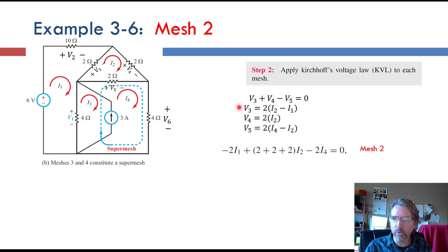Pay attention to the Ohm's law sign convention here when you're subtracting your currents and labeling the polarities. When we combine these together, though, we get this equation here, and you can see that the pattern we've been looking for all along holds, and it really is independent of how you label the polarities here, because then you use Ohm's law and it all works out in the end. But we've got the I2 mesh, positive terms on I2 and negative terms on the other currents.